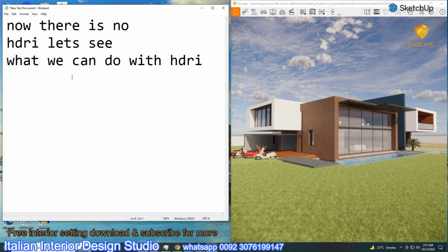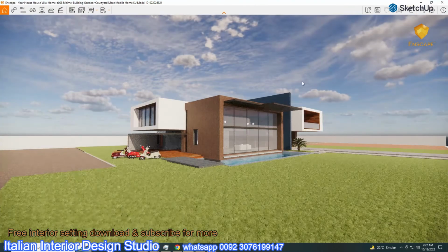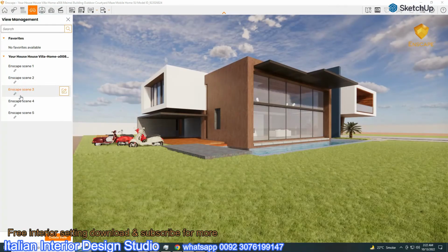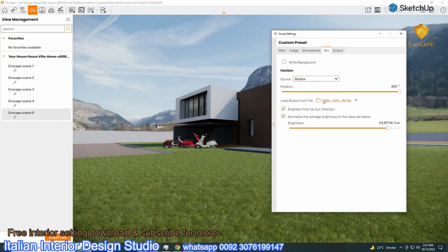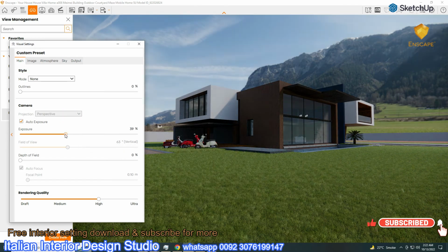So if you want to use a darker surface, especially on the floor, then you have to use more light inside of the model. I mean interior lights like spot lights or omni lights, this kind of lights. So you cannot get the benefit of HDRI or sunlight if you have a darker surface on the floor and the wall.